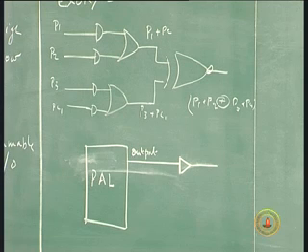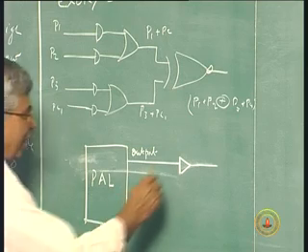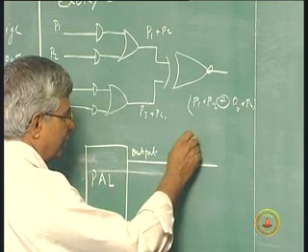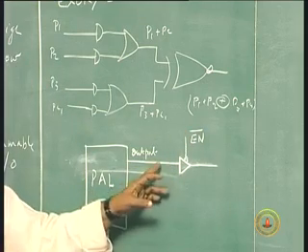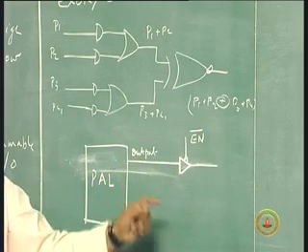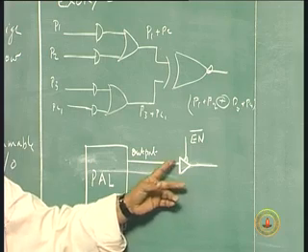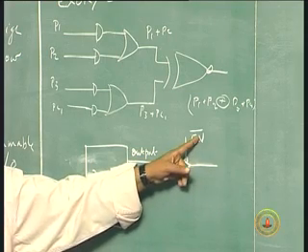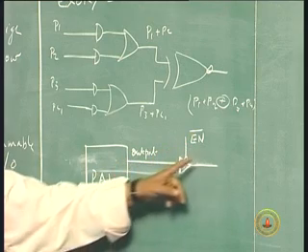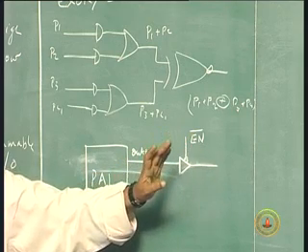You talked about tri-stating, remember, enabling a gate and disabling a gate, we talked about it. There is a state called high impedance state. So, I am going to put an enable here. So, I can electrically disconnect this, even though it is physically present. When enable is 0, the output goes through as an output.